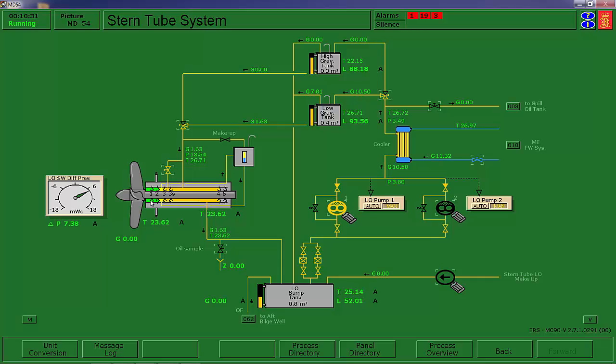So to prevent that, in many cases you'll see this is your stern tube, and that is oil lubricated with the gravity tank feeding down, and there's your flow rate down into this and lubricates that bearing. And remember, it's got to take the full weight of the shaft plus the overhang propeller. Now, if the oil differential pressure is too high, that could force it past the lip seals into the environment, and you have an oil pollution incident.